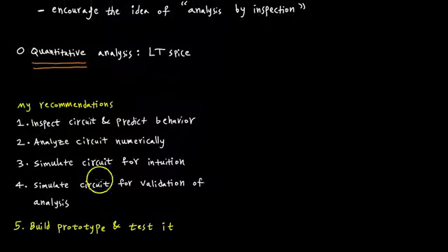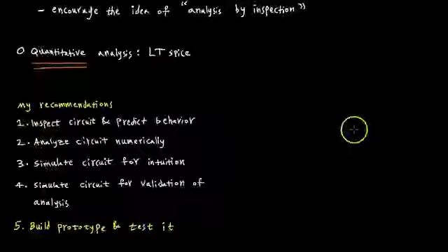And the last step is optional, but it's a very, very good step, and if you're in school, this would be almost required. In most cases, it would be required, which is to build a prototype and test it, because the real world is not the same as a simulation. The simulation does not take into account parasitics, temperature. It can, but it usually is not as complex as the real world, with its many variables, the noise, variation in the supply voltage and current, and so on and so forth.